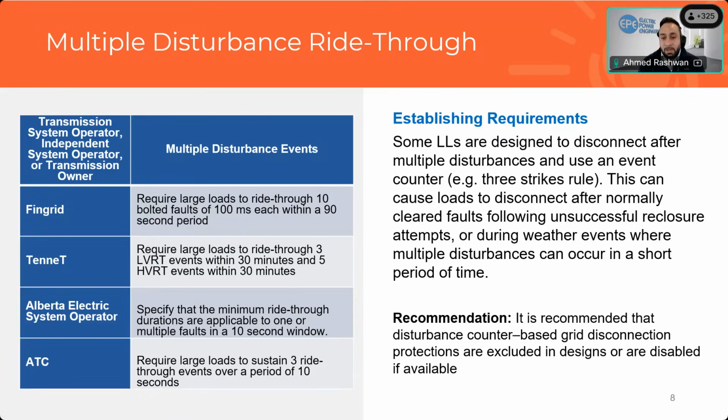And so what we're recommending here is to disable this counter-based logic if possible. If not, make sure it's coordinated with what you expect during normal operations, but also what you want to see during more extreme events when you have storms coming through your jurisdiction.